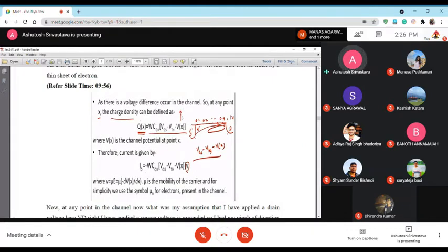Basically, the charges, as we have talked, beyond the threshold, beyond the pinch-off voltage, this inversion layer starts to pinch from drain into the source, and then you have a higher concentration here, while there is no direct connection to the drain via the source and the inversion layer.